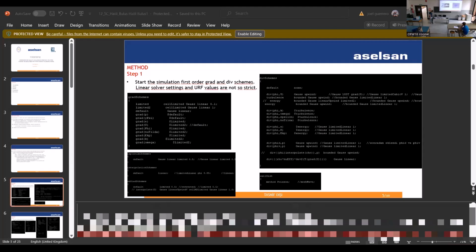I wanna give you some critical information about the mesh. It has a Y plus value of about 85, and 12 boundary layers were created to capture the gradient changes on the wing very well.